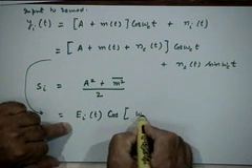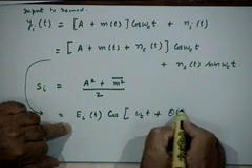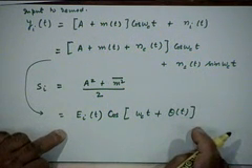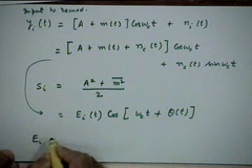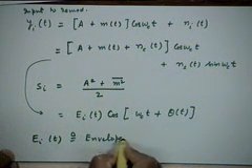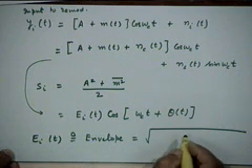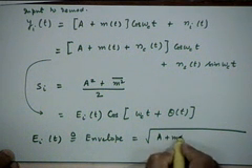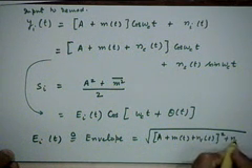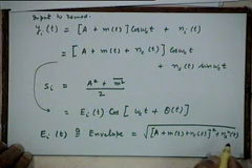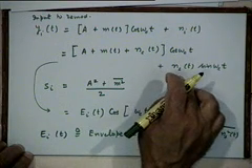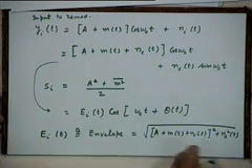I can always write this trigonometric expression in terms of this trigonometric expression, where E sub i of t, which denotes the envelope, will be given by the square root of (A plus m(t) plus n c(t)) whole square plus n s square of t, and there will be some theta t, which you can write as tan inverse of n s upon this entire thing, but that is of no interest to us.